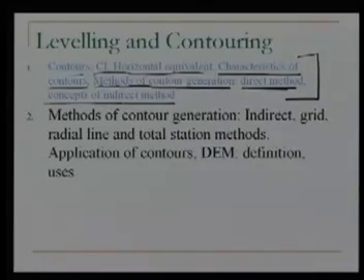In the case of the direct method, we are standing on the ground on a point where a particular contour passes through. So basically that was a trial and error method. We try to stand on the contour, we try to follow the contour, and we keep recording it, the direct method. We also saw the disadvantages of that. It's very difficult, time consuming, based on trial and error. So can we do something different?